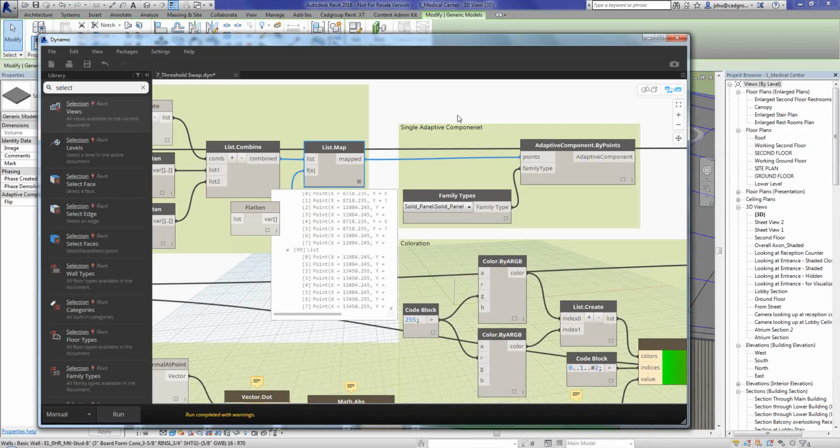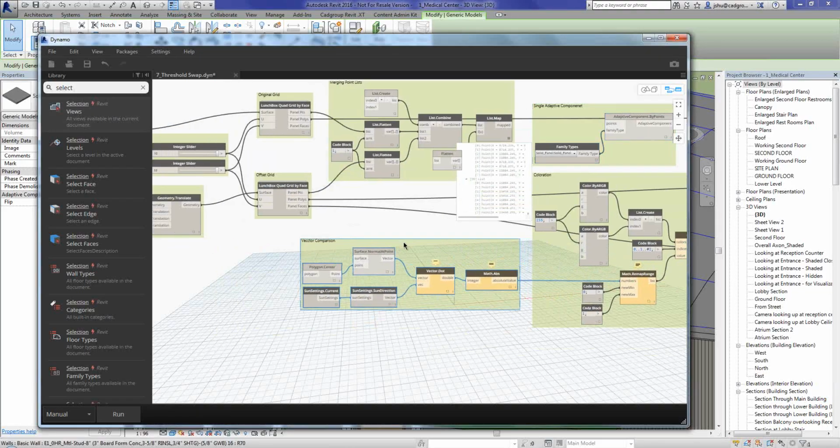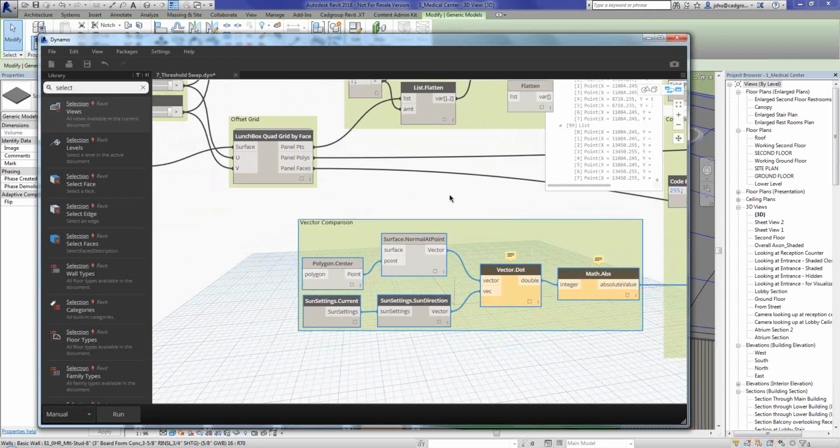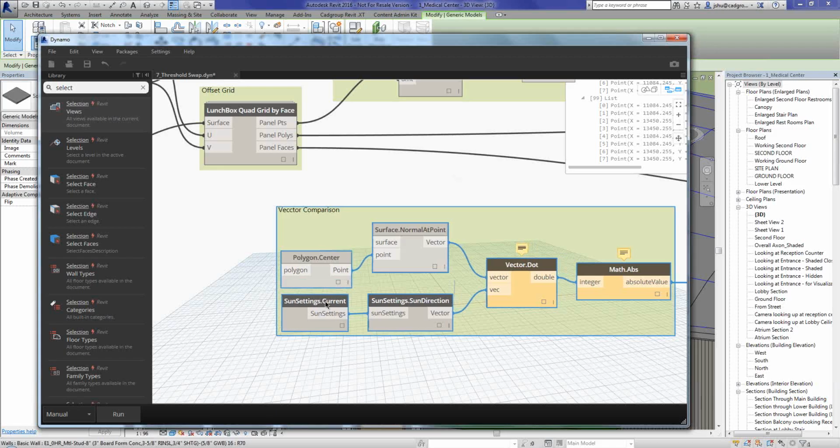And so all of that has been pretty easy. If we stop here, that would just be too easy, wouldn't it? So the next thing I'm gonna show everyone is doing the solar analysis on each and every individual panel. The theory behind this is quite simple. Revit is software that's designed with the sun path in mind, as you can set any given position of the sun at a given time. So we take the sun position and we turn that into vector information.